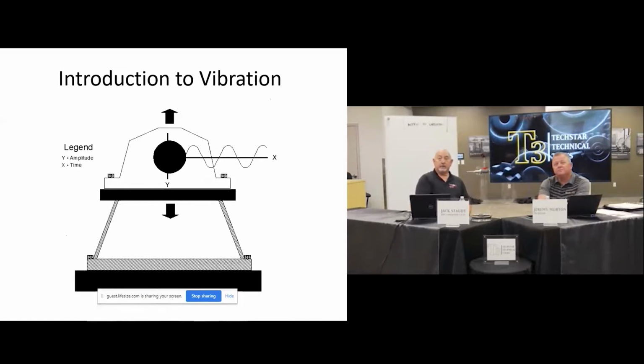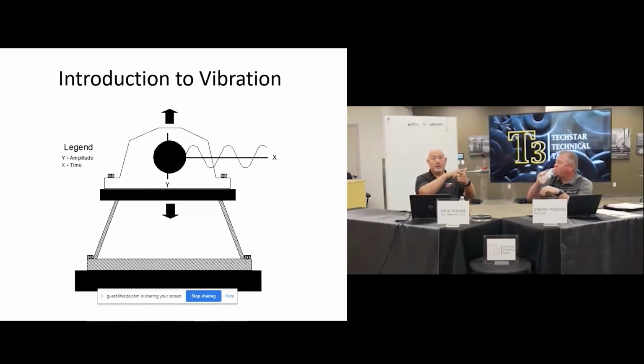So, a little introduction. We look at vibration where it moves left to right. Our amplitude is our y-axis, our frequency is our x-axis. Just another key note, if you're looking at Bentley Nevada instruments, this is also how the probe orientation is, where you have your Y probe and your X probe.